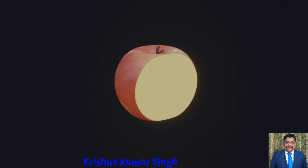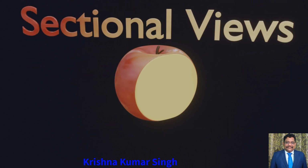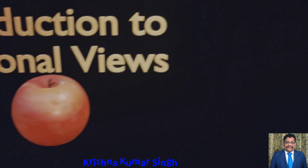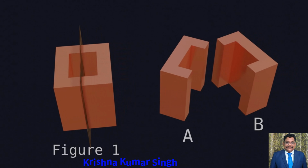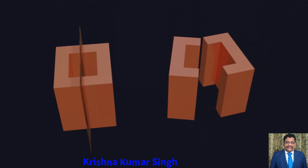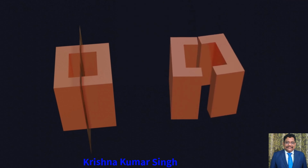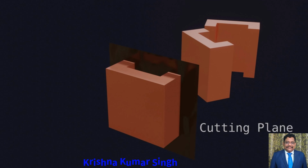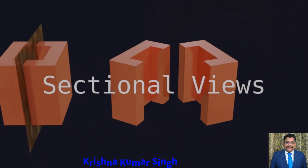So in this video, we are going to discuss sectional views. Let us first discuss what actually is sectioning. Let's take an example. In this example, two blocks A and B result when the block in figure 1 is sectioned. So basically, sectioning is the process of drawing the internal configuration of an object by cutting it apart. And the plane which cuts an object is a cutting plane. Remember that the cutting plane is an imaginary plane taken through the object. Views obtained by sectioning are sectional views.